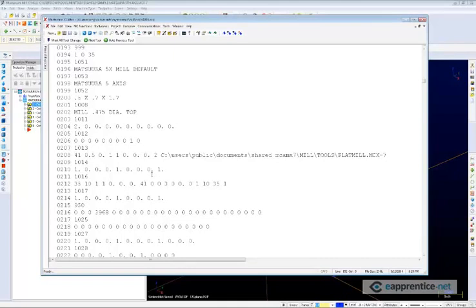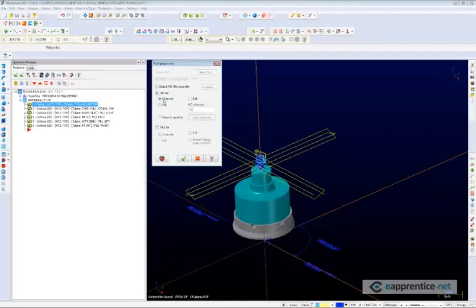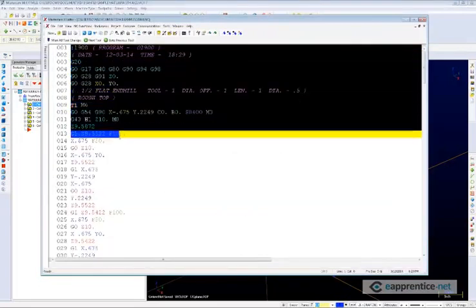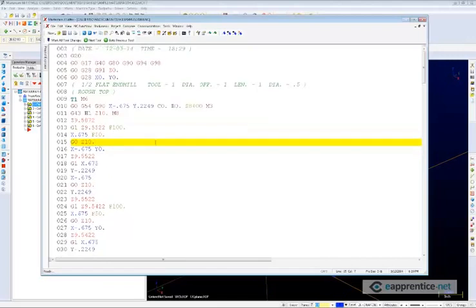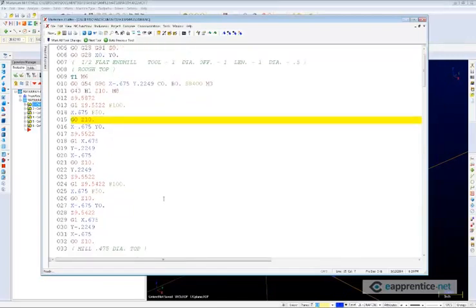That's what the post processor does. So it takes this information, and based on your machine type, it's going to translate it into machine code. So if I select these operations again and select NC file overwrite, we're going to output the machine code. So this now runs through the post processor, and we get data that is formatted to run on your machine.